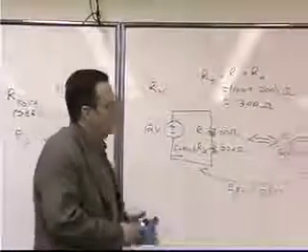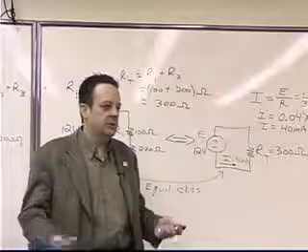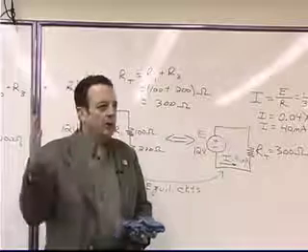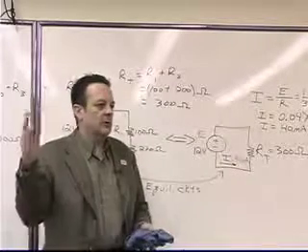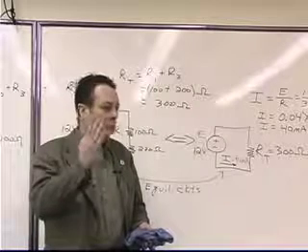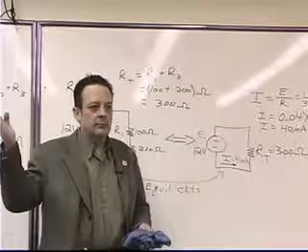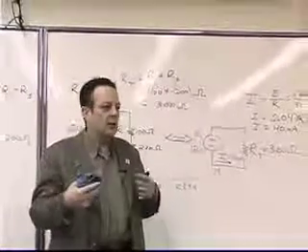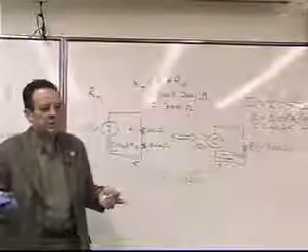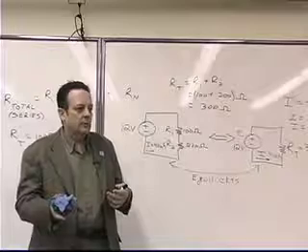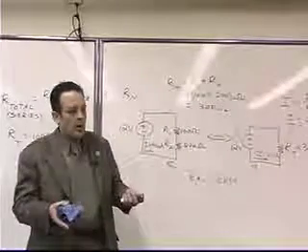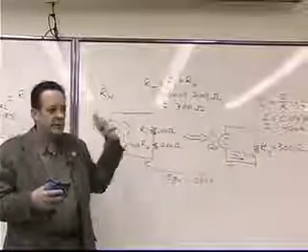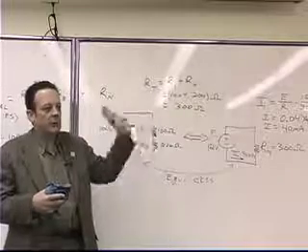Slightly more complicated series circuits are not difficult. The reason they're not difficult is because all you're doing to simplify them is adding algebraically. You're taking the numbers in ohms of the loads and just adding them up. When we get into parallel circuits, the formula gets a little bit more complicated, but it's not hard if you have a calculator and know how to use it. And then the combination circuits are still just a little bit harder, but again, you can simplify them down into just one resistor, and that's our goal.